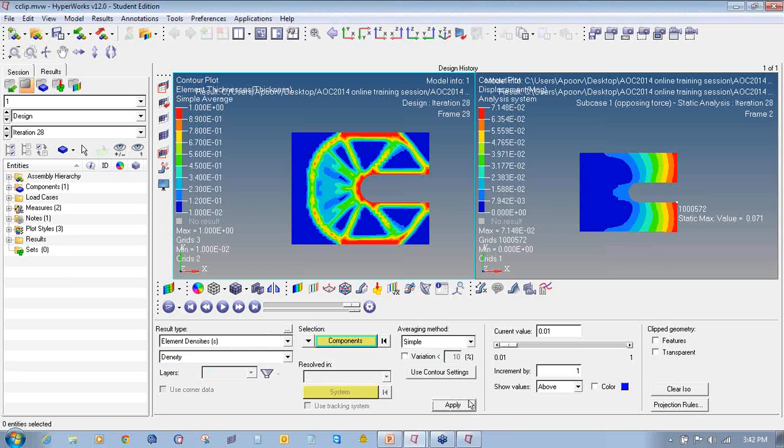Where the element density is high, that area you should take care of. You should have a blue region somewhere on your model, at least the light blue region. It should not be like this, as it may or may not fail. But with the blue one, the chances of failing will be less, not the dark blue but the light blue one.